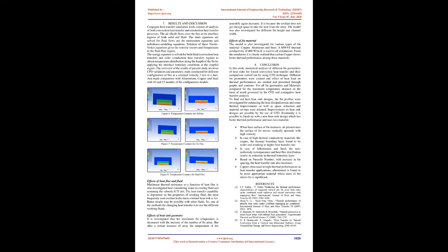The microchannel has discrete zones as solid and fluid domains. The inlet boundary is a velocity inlet, and a pressure boundary of 0 gauge pressure is applied at the fluid outlet for the exit boundary condition. The interface is defined to enable fluid flow visualization across the MCHS. Since heat transfer through conduction takes place along the copper solid wall, and convection between the heated bottom wall surface and the liquid, the meshing is made very fine in order to simulate conjugate heat transfer, which is a combination of conductive and convective heat transfers.